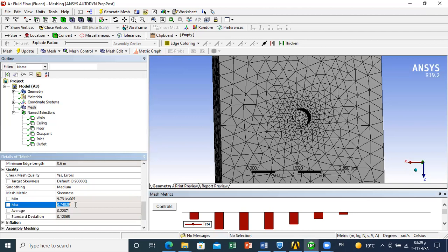This will complicate the meshing a lot, because you have to consider all curves of the human body, the different parts: the head, the torso, the arms, the feet, etc. So you need to follow all curves. This will complicate the mesh, and maybe you will have some zones with relatively high skewness. So you should try some strategies, and we'll see together what strategies can enhance the quality. Here it's already good.